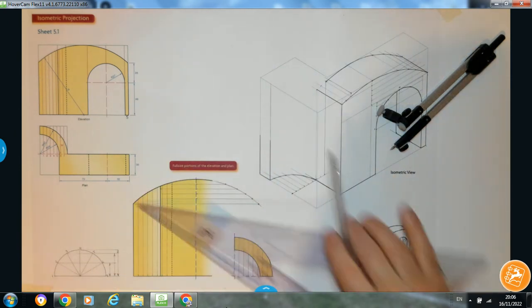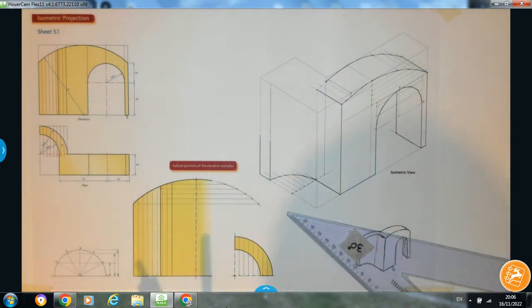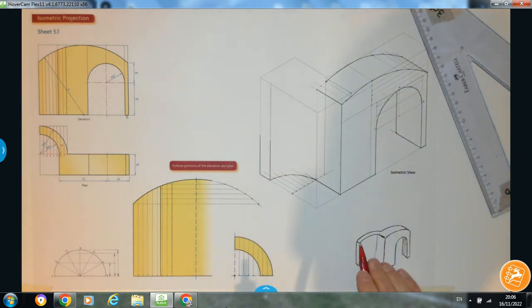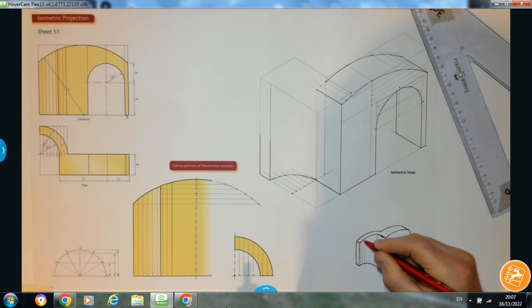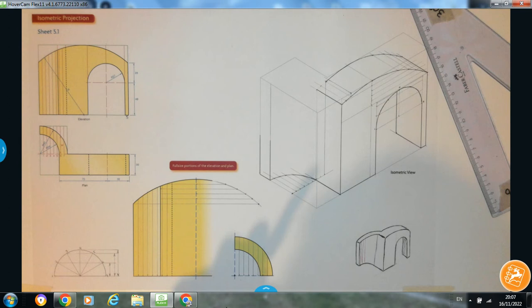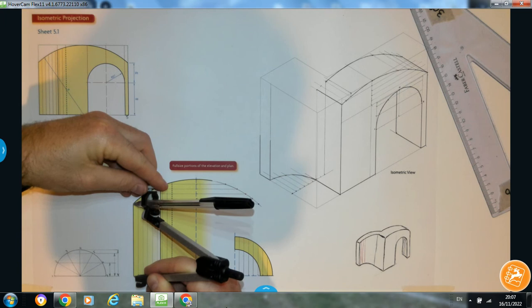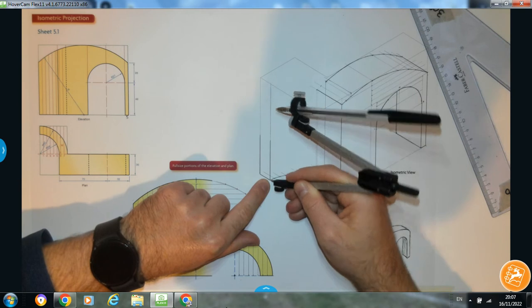To get all these points, I'm going to take the heights up. To get the very first one on the outside, which would be this one right here, I'd have to have a series of other points. So there'd be a line going up like that, a line going up like that. All of those 5mm lines help me identify a point. So I'm going to take the vertical distance off my object, come to the point here, and mark it up.